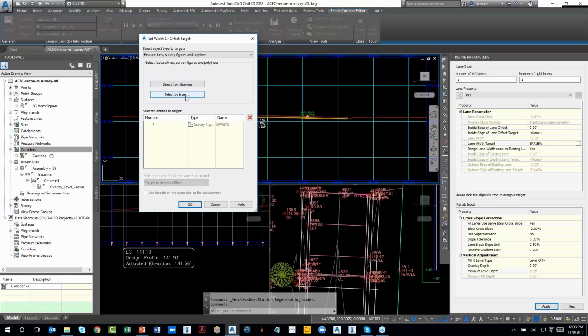So yes, you can have multiple of them, and they don't have to be contiguous, one after another; there can be a gap. Sometimes you may have overlapping ones, and even that works, because Civil 3D added this feature maybe 5-6 years back, maybe 8 years back. Even if they are overlapping areas, we take the nearest; see the control at the bottom. Do you want the nearest offset or farthest offset? You can choose what rule to follow. If you wanted to jump sometimes nearest, sometimes farthest, interactively we don't support that. But generally, if you can follow a rule, you can do that too.